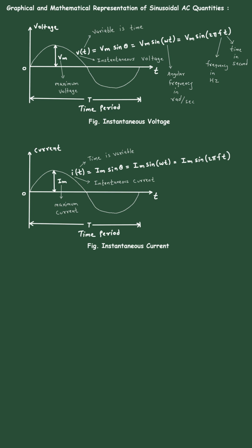So, putting this all together, the equation V of t equals Vm sine of 2 pi f t tells us the instantaneous voltage at any point in time for a given frequency and peak voltage. As time increases, the voltage rises smoothly from 0 to its peak positive value, then returns to 0, drops to a peak negative value, and finally comes back to 0, completing one full cycle. This behavior continues endlessly in a perfect sine wave.